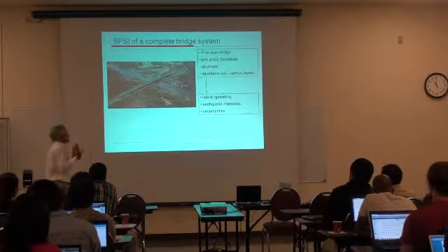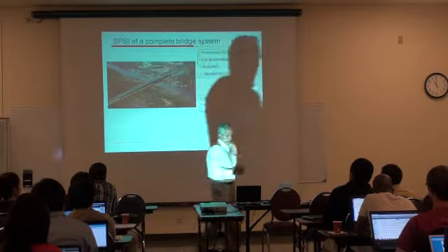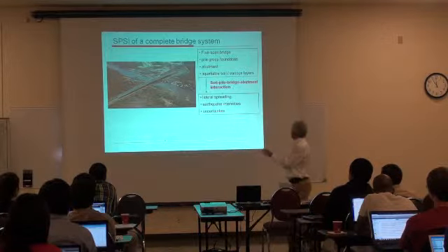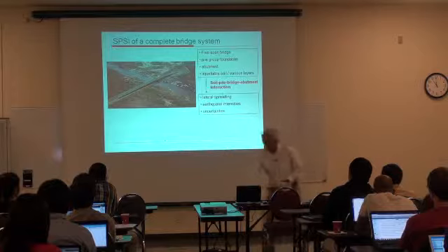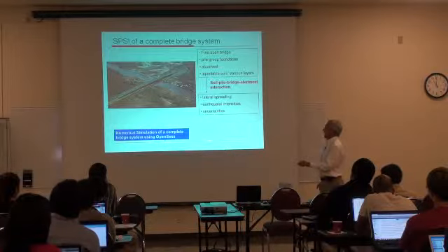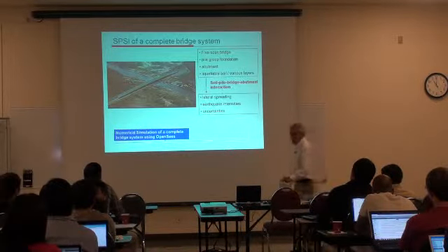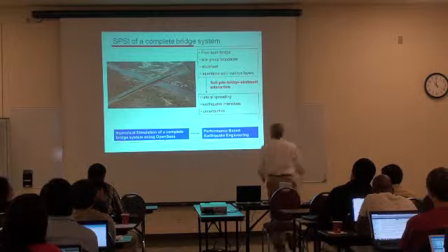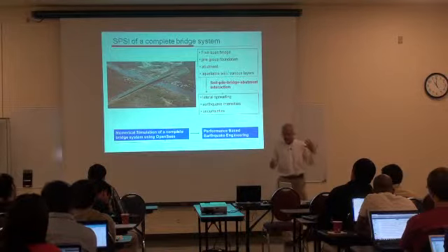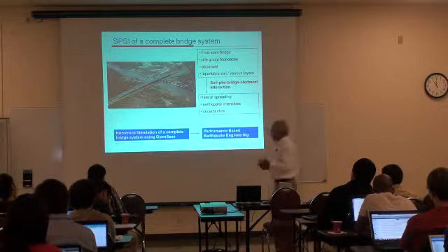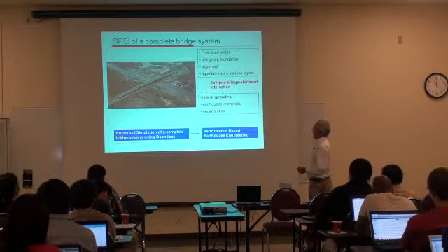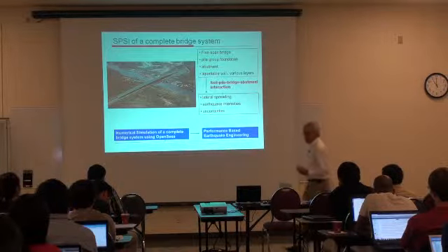And the big problem is, how do I model it? I have to compromise between the type of model that I can develop for this. So soil, pile, bridge, abutment interaction has to be modeled. We wanted to do the complete numerical simulation of the whole system using OpenSees. And we wanted to do also performance-based earthquake engineering analysis. That's why we were using uncertainties. And we wanted to develop some fragility curves and some hazard curves using the PBEE method that was developed here at PEER.